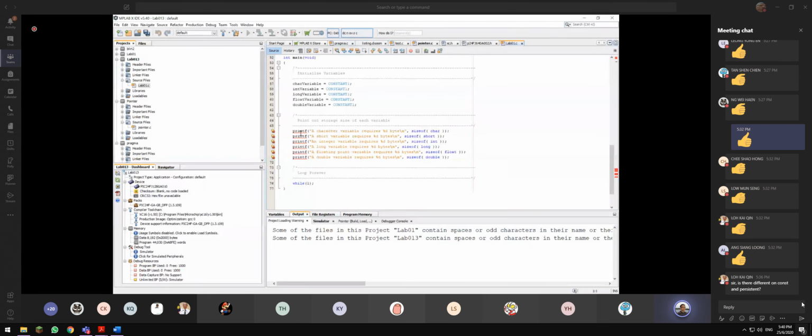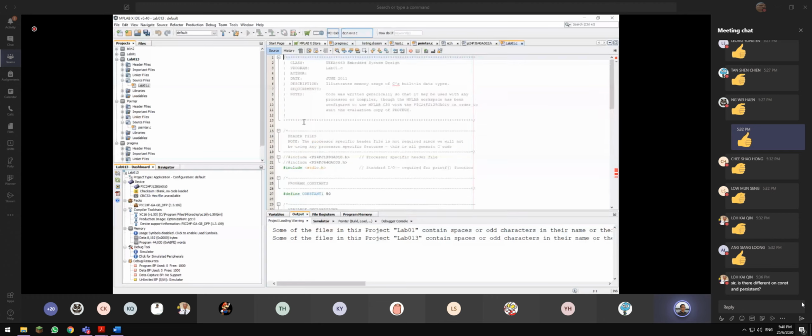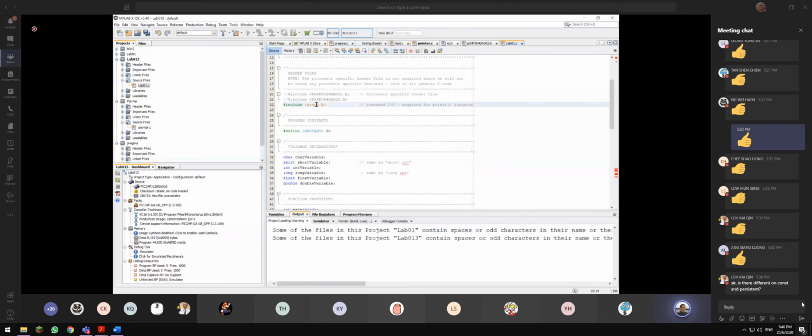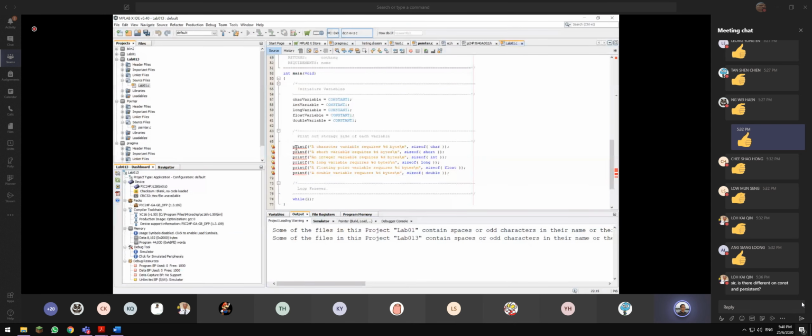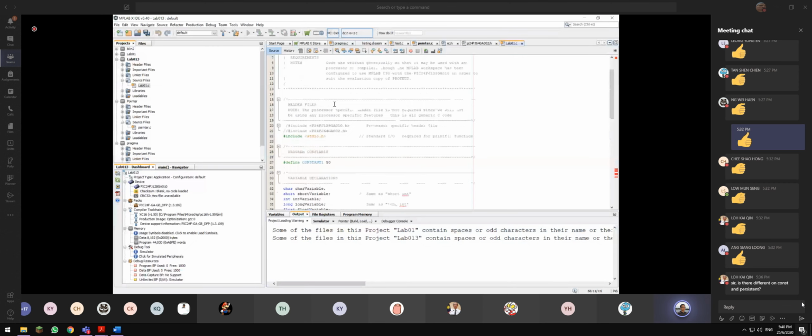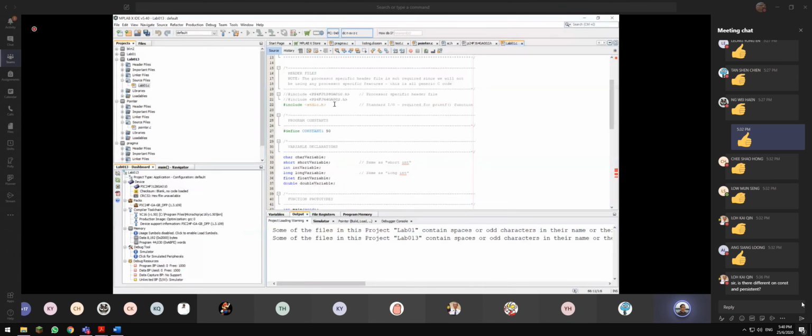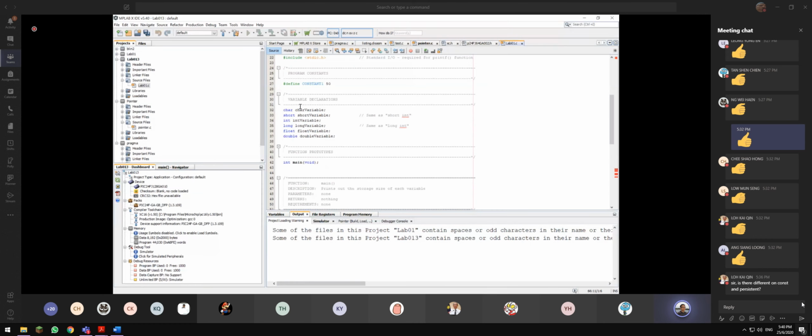Class, there is printf. Remember printf is tied to stdio.h. Normally it's not recommended to use printf because once you use it, it consumes a lot of memory space. However, this chip with 128 has a big memory space, so it's perfectly all right.